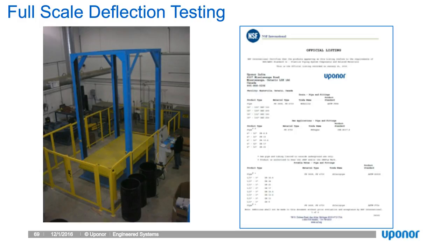So that deflection testing is actually the basis of our design, and it's very important for any manufacturer that produces polyethylene pipes, whether it's structural profile wall or solid wall, to be able to show that their deflection testing of their material meets the ASTM, and their design is in line with that empirical data.